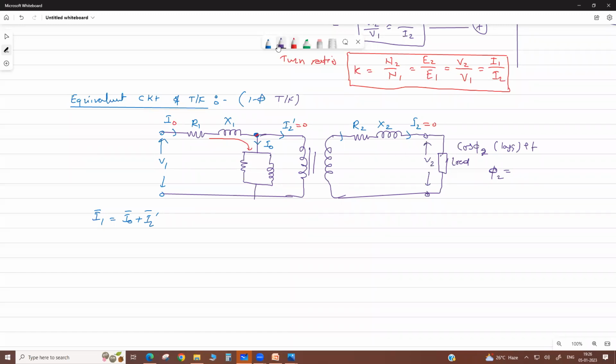Now here at no load, the induced voltage is E, here suppose E2. At no load, the terminal voltage is E2. But as we put the load, there is a drop in the impedance, known as Z2. This is Z1, the impedance of primary and secondary. Due to this drop, the terminal voltage is reduced. So E2 is higher.